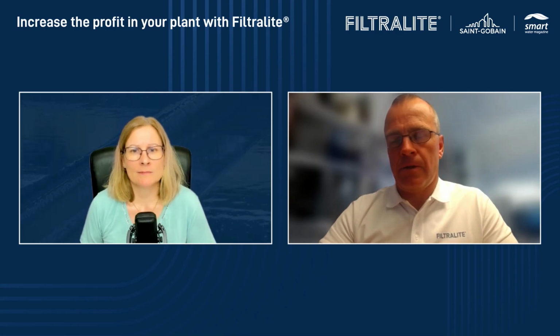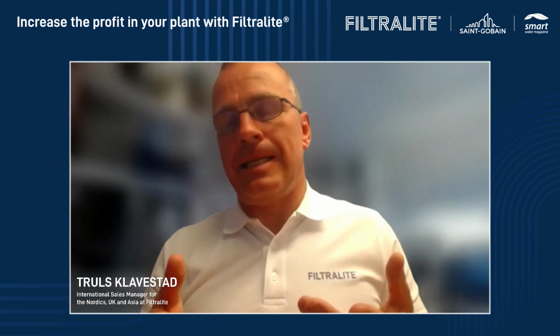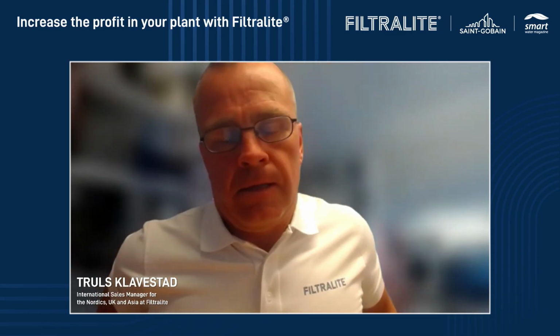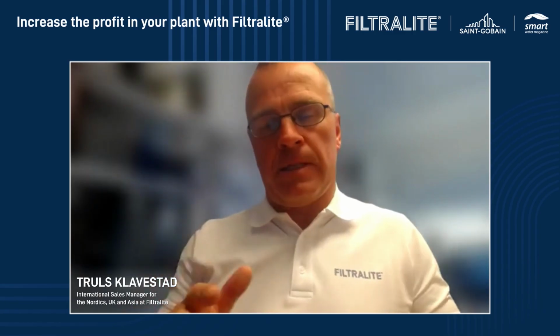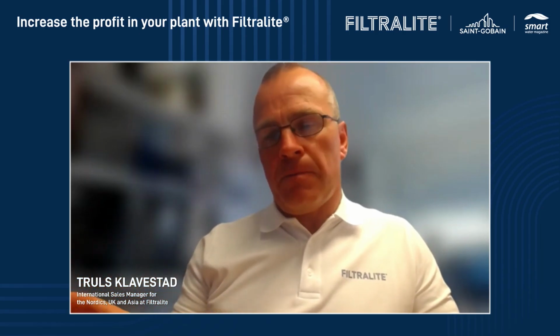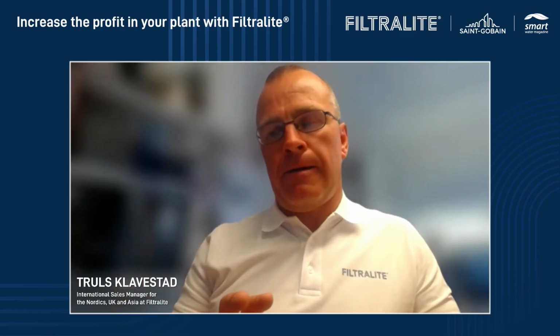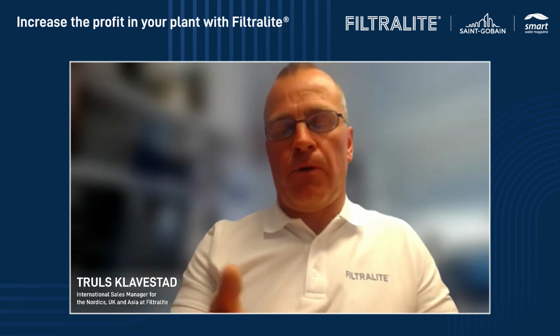Yeah, it's a good question that I get many times. I will not recommend Filtralite for that, but it's not a so straightforward answer. There is something with arsenic that Filtralite itself cannot do, but as I said in the introduction, we have some other special products, for example for phosphorus removal, and we have a product called Filtralite HMR, which is more like activated carbon. So this is a typical case for this kind of Filtralite product.